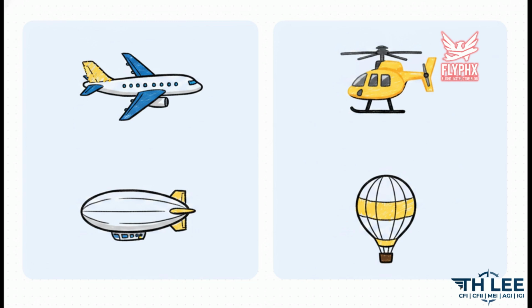Rotorcraft display marks horizontally on the cabin, fuselage, boom, or tail. Airships must place them on the upper right and lower left horizontal stabilizers, and on the bottom half of the vertical stabilizer. Spherical balloons display them diametrically opposite at the maximum horizontal circumference, while powered parachutes place them visibly on a structural member. The shape dictates the placement.